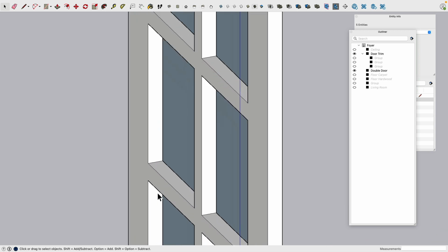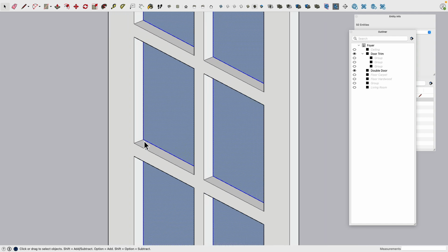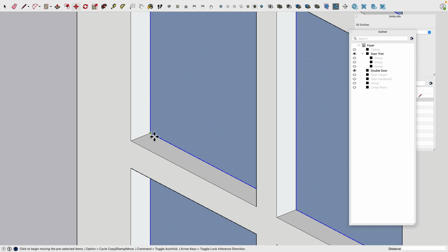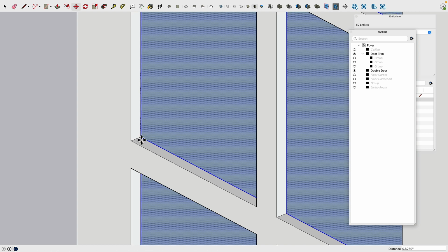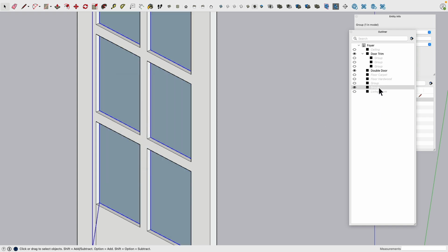And I'm looking from this view now. Double click with shift. I'm double clicking like there's no tomorrow. But do not double click into the door. We just want to double click all the window parts, and we move this to the midpoint. So I select here, where's the midpoint? There it is, very good. And then all this, right click and group.